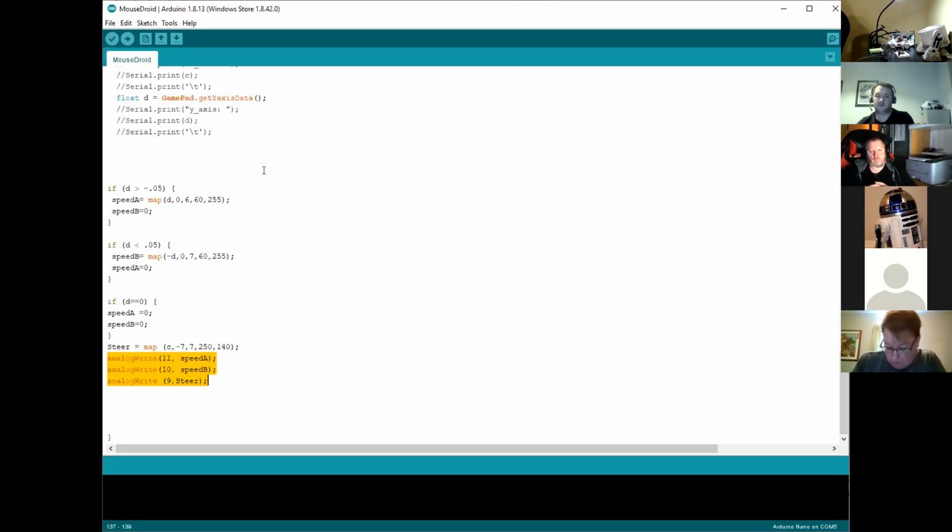On the speed controller, what you tend to find is they'll all have different ways of doing things. On this speed controller that I'm using, you can generally see, to be honest, it's not necessarily looking too deeply in the specs. It's just looking at what the inputs are for the board, and it'll have forward PWM and back PWM, and you go, okay, now I've got to send 2 signals for a forward and a back. Another speed controller that I use has 1 speed, which is speed PWM, and then a forward and back 1 or 0. So you send the speed on 1 pin, and if you set the other pin to high, it'll spin it forward, and if you set it to low, it'll spin it back. So it's just dependent.